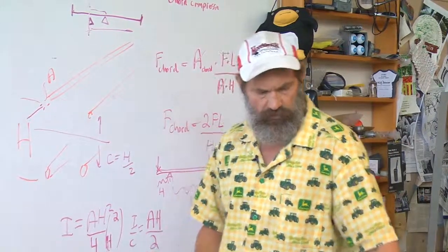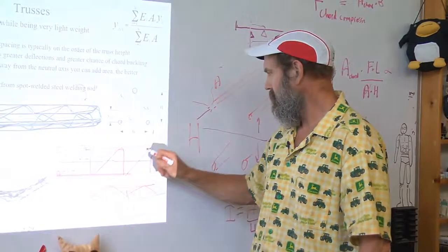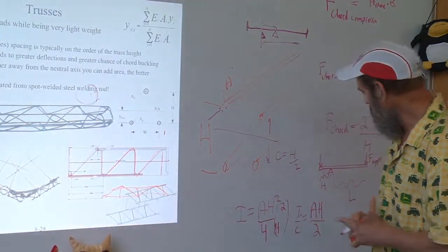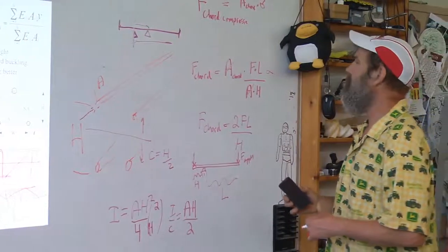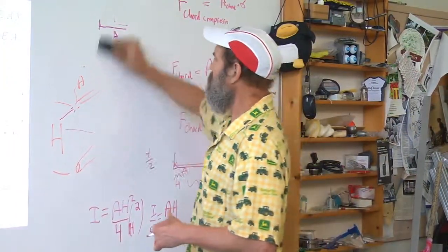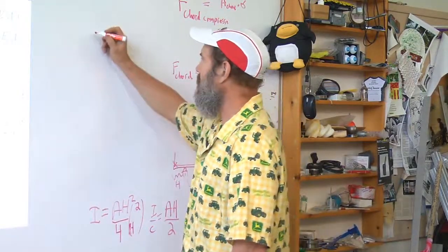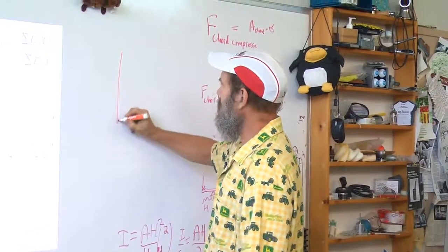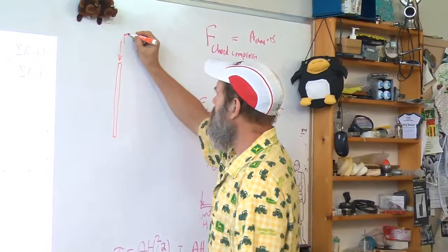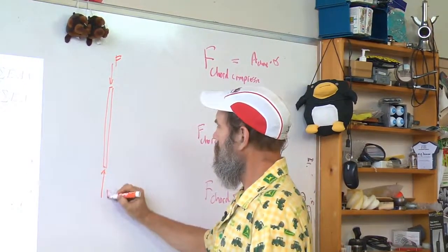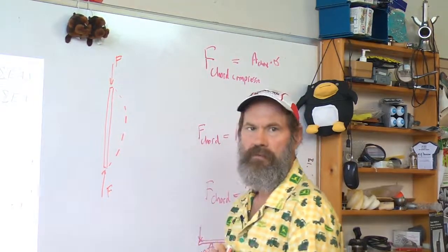How does that get to where these diagonal braces go? Well, now you get back into good old-fashioned column buckling. And remember this from topic 5 even. We talked about stability of columns or shafts. If I have a column and I push on it, how hard can I push before, bam, it buckles?